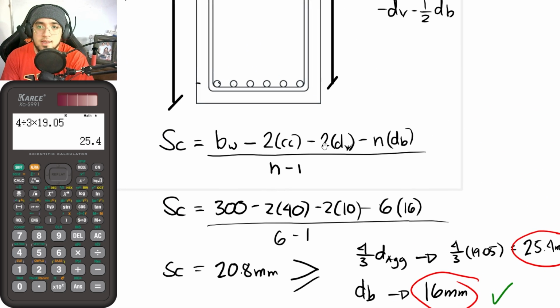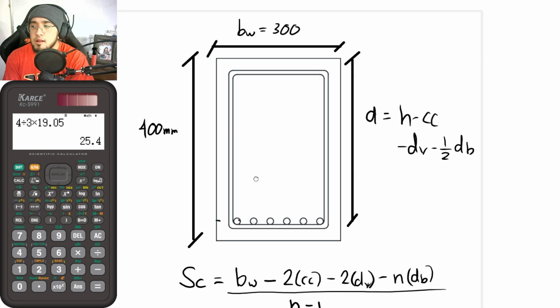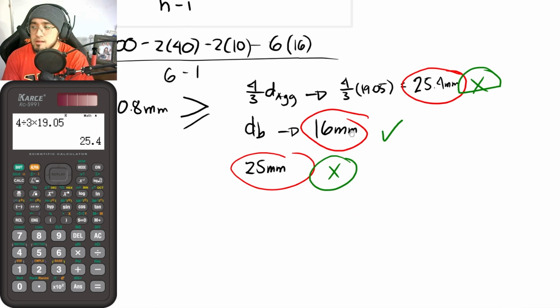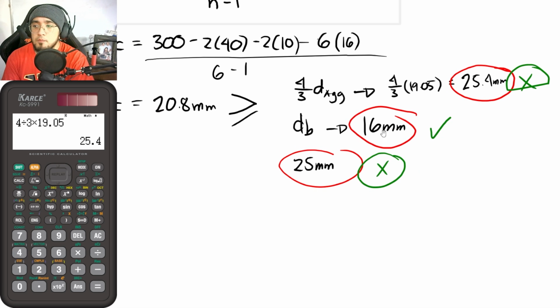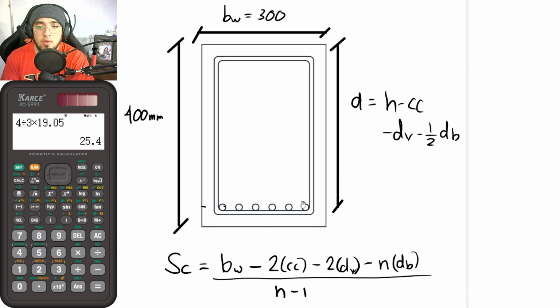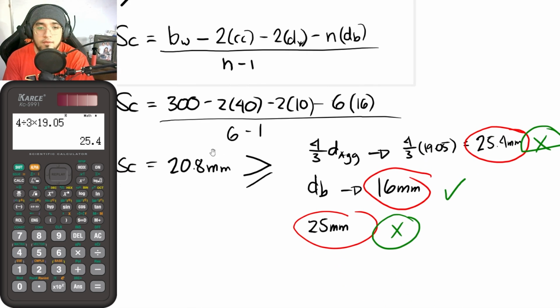So even though theoretically speaking 6 rebars can carry the required moment, according to the code it is not allowed. Okay? So what can we do now? Since we have solved for 6 bar diameters in one layer, in order to have a greater spacing, one method is to redesign your beams in such a way that your beam width would be larger. So increase your beam width, or even increase your beam depth.